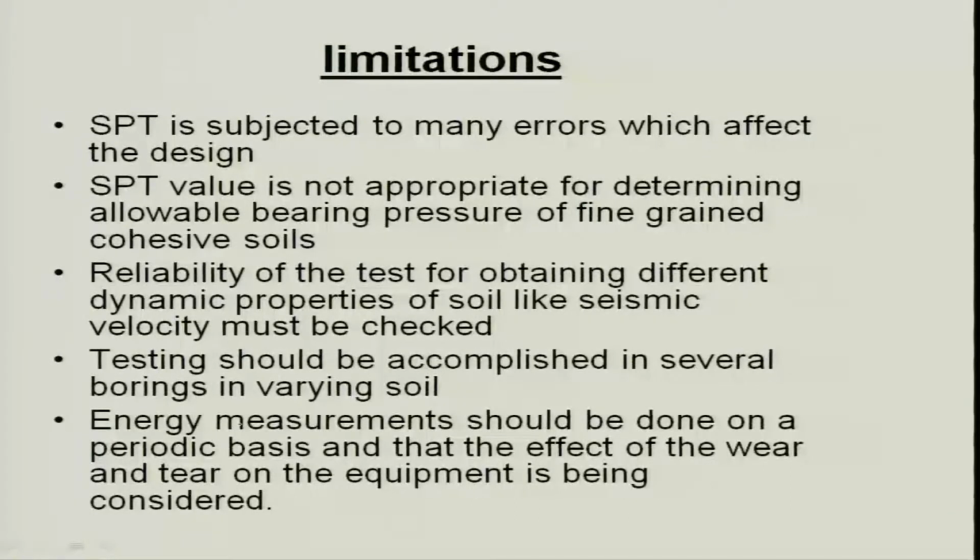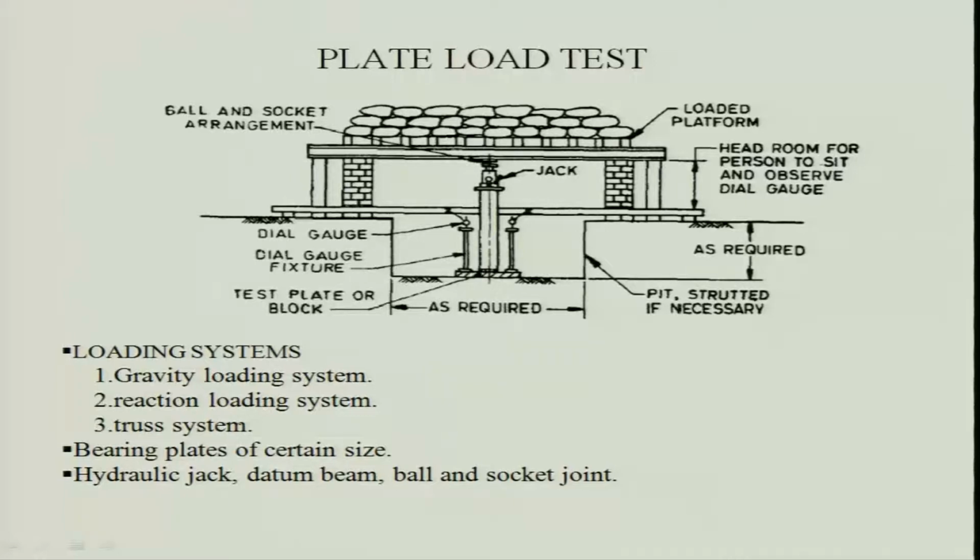Now, last class I finished the plate load test by showing your diagram, by plotting the diagram. Now, it is a visual. If you see this, this is how it has been done. Look at here, this is your test pit, this is your plate, 300 mm to 700 mm, this is a hydraulic jack, and this is your reaction beam.